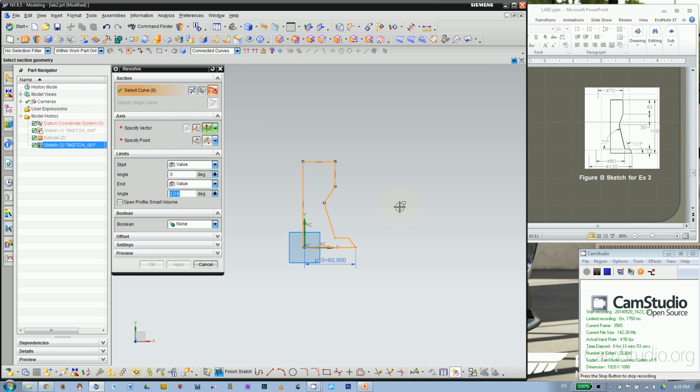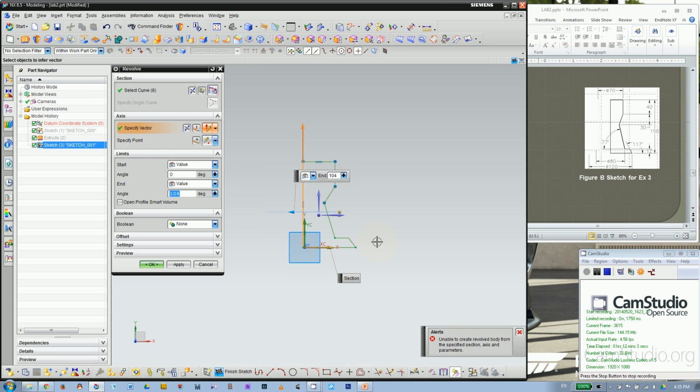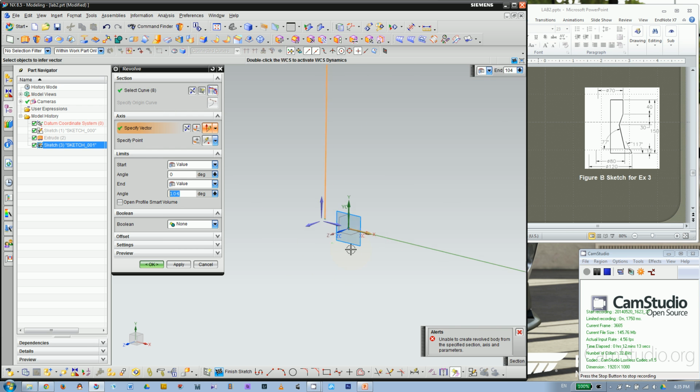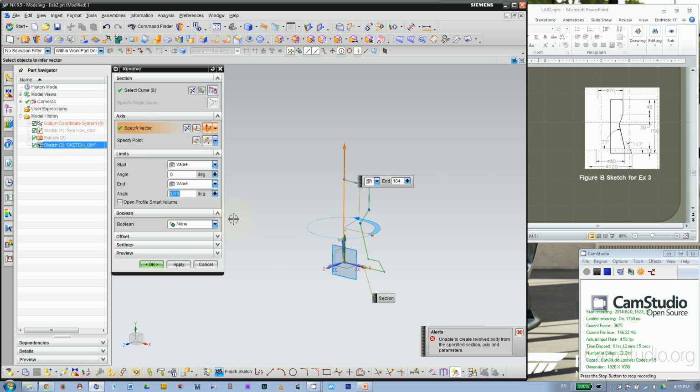And try to extrude or try to revolve this. I'm gonna revolve without putting dimensions first. Have everything, then we can specify the vector, maybe this line. Okay, and ta-da, I'm able to create this section. Why? Because you have this little opening here. Let's try to revolve on y-axis, maybe.